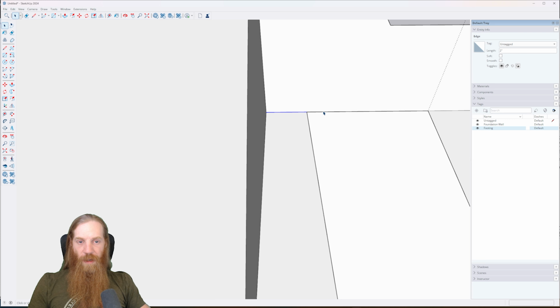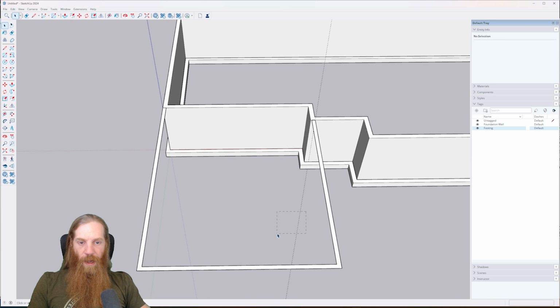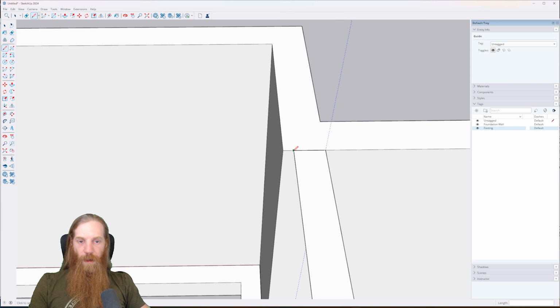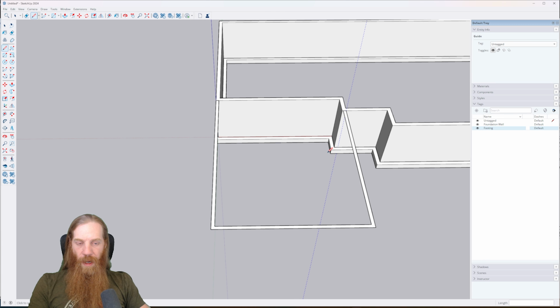You can see I was able to select, now that we have a line that we butted into a line that was already existing, it split that line into 2 different pieces. So now we can just select the piece we didn't want, hit delete, and that's no longer there. Okay. That was just because when I made this line originally, I accidentally went all the way to the corner, not thinking about what I was actually doing, because we only wanted 6 inches, but I went all the way to the corner, which was 8 inches. So it left a 2-inch length of line right there that we didn't need. So that's why I selected that and deleted it. So now we have that.